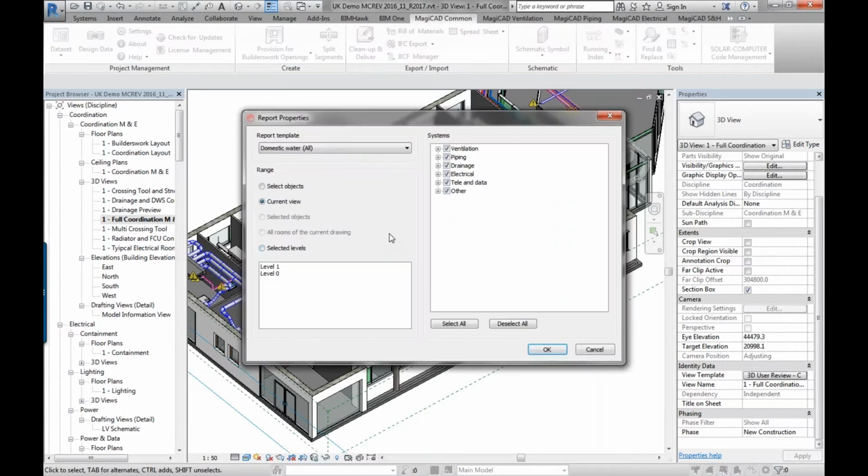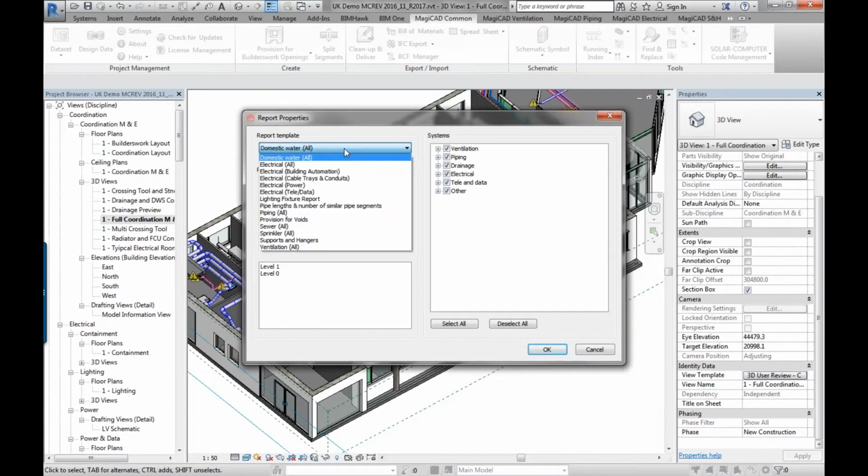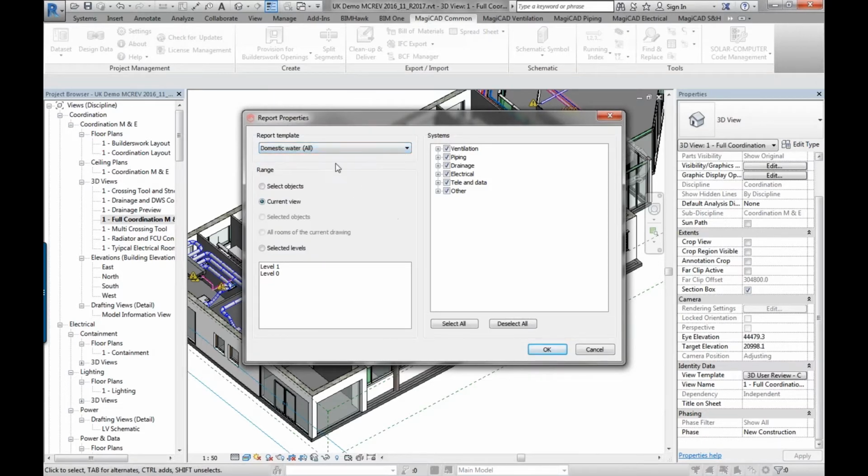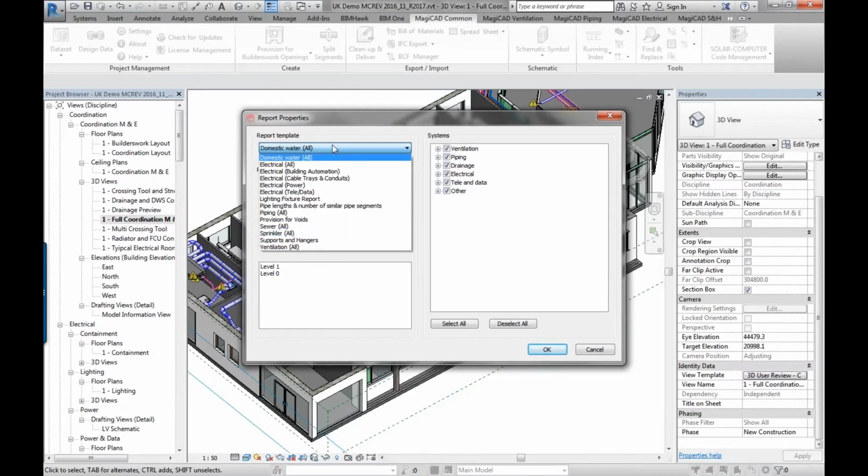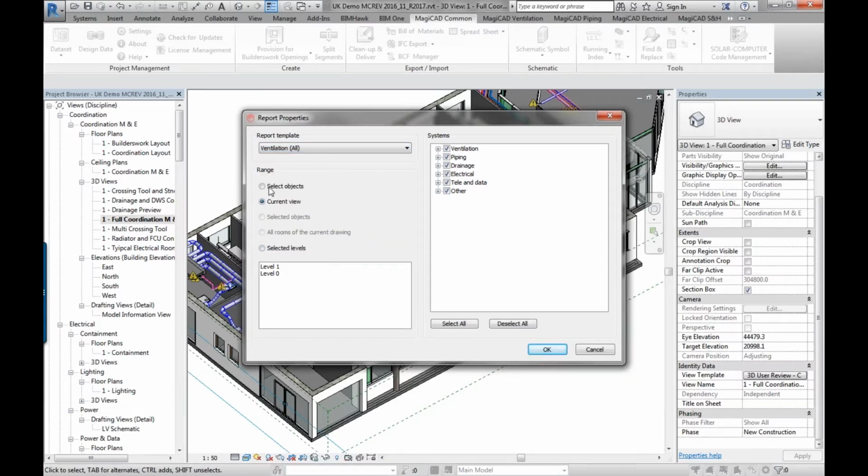And then lastly, you can also strip out schedules and legends if you don't want those to be available as well. So you can strip out whatever you want down to the bare bones of a model. But once you've done it, you just save the selection file, like Save As, choose whatever you want to call it. Then the following week, if you do the same thing every week, all you do is just load up that selection file. It'll remember all the settings that you had in these tabs here. So it's a very, very handy tool included in our software. Makes life a lot easier on a Friday when you're trying to rush a model out the door.